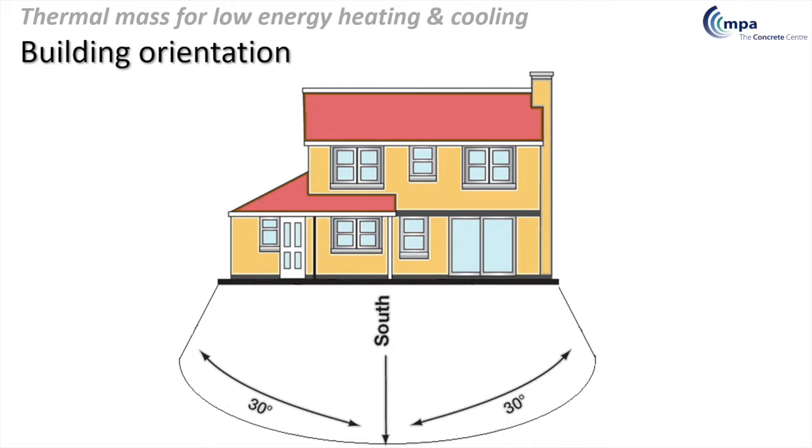and I think that also includes orientation. It's really great if you can orientate buildings on a north-south axis or within about 30 degrees of south. And there's a number of reasons for doing that, but essentially it boils down to good daylighting, it avoids glare, it makes shading on the south elevation really easy, just using deep overhangs for the roof, for the first floor level, or maybe balconies or brise-soleils. Any kind of overhang really will keep out the high-angle summer sun to prevent overheating. But it also allows, importantly, some useful passive solar gains during the heating season.